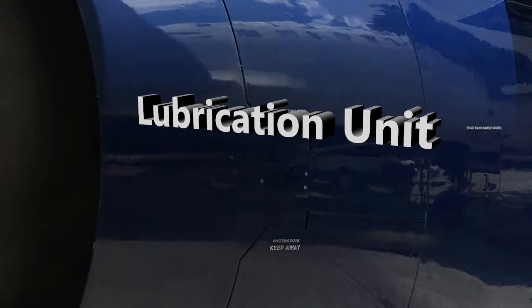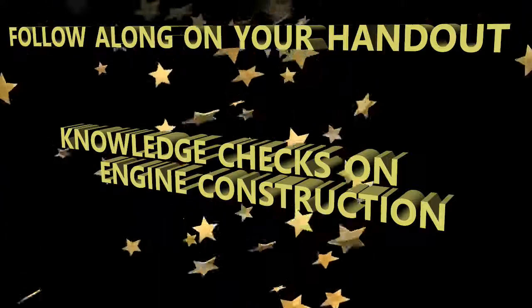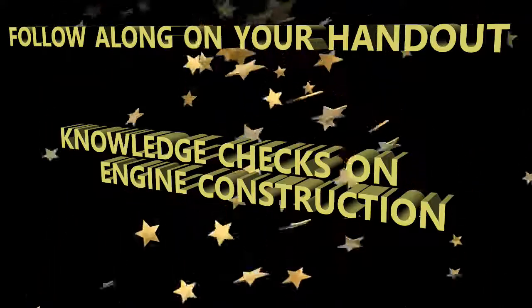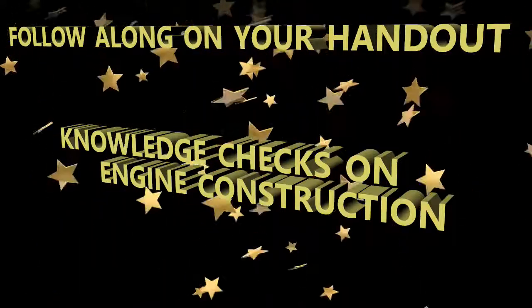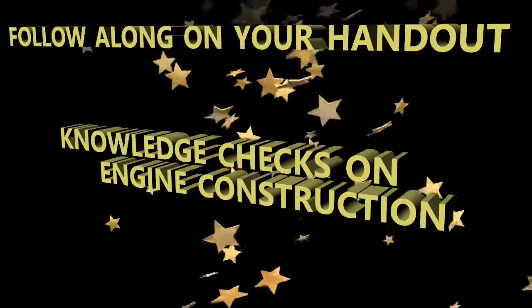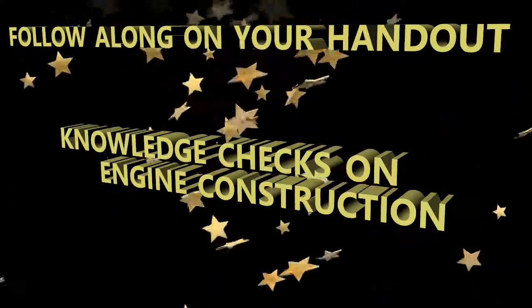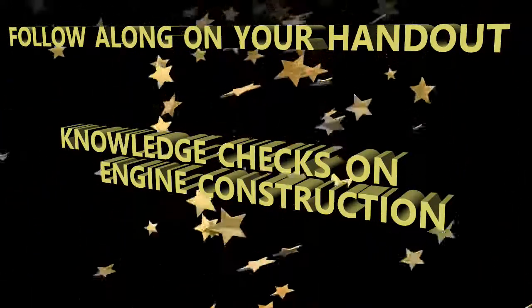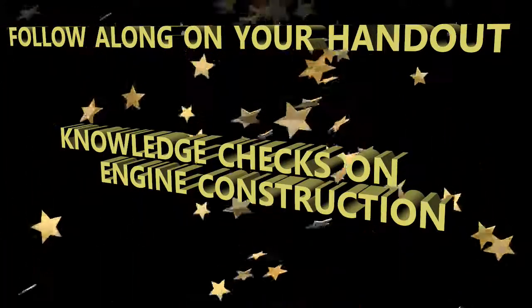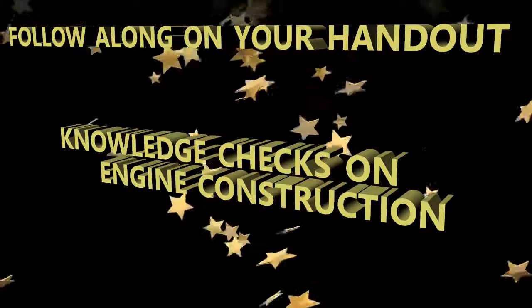Okay. All right, let's get some questions under our belt right now. Let me throw out several to you, just so you have an awareness of what kind of questions to expect. In order to replace the combustor, and I didn't mention this earlier, but the combustion section, which has the fuel nozzles connected to the combustion area, let's say you wanted to replace the combustor. Do you have to remove the fuel nozzles? The answer is no, you do not have to remove the fuel nozzles to replace the combustor.